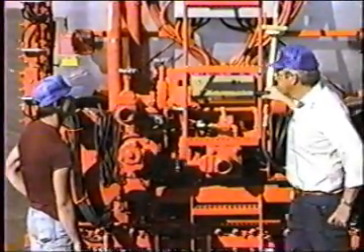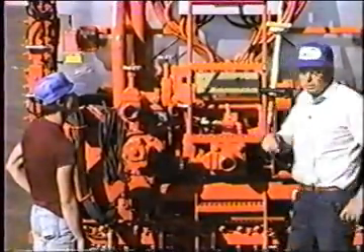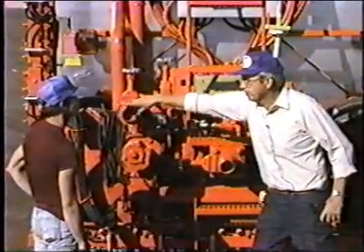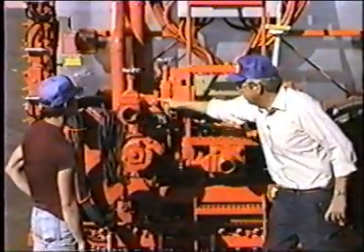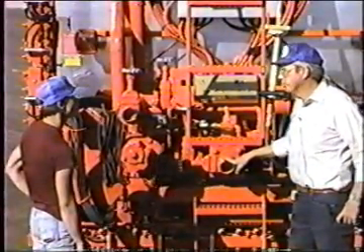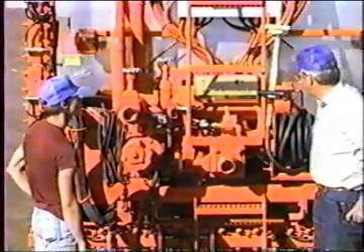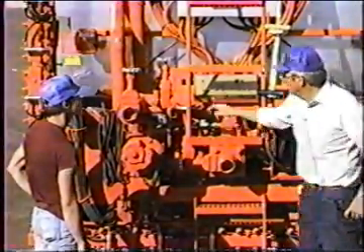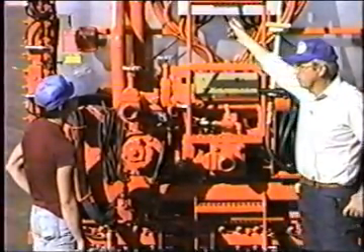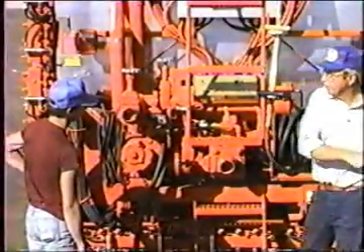Another situation, maybe we want to move material from a tank over here to a tank over here. In that situation, we could hook on here from that tank. We could go in the top, out the bottom. Since we're going that direction, our pump is going to be in reverse. We're coming out here to this tank. That tank valve would want to be closed, bar valve closed. Everywhere we don't want it to go, we want to close off. We just want this path open through here.